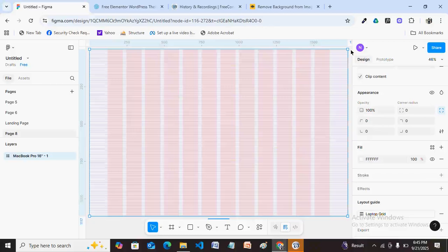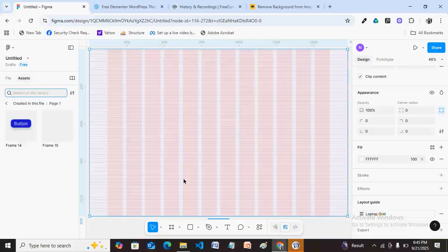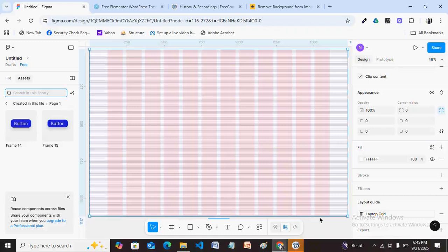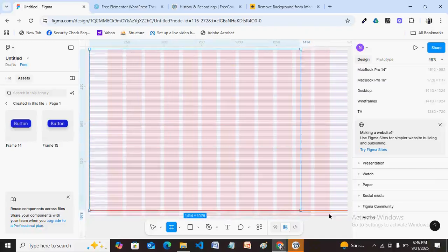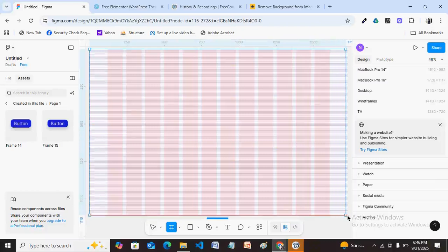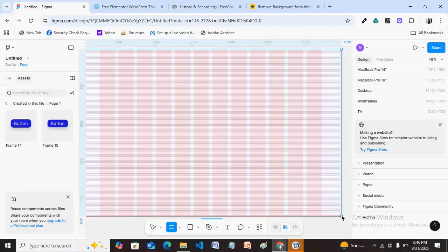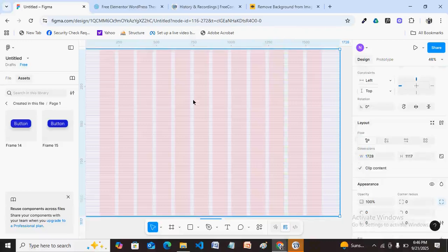So what I'm going to do is go to my assets. Before that, you notice that we have a kind of blue background and image on this particular section of the design we have followed. So I will come over here now, create another frame and give it the same size of what I have here. Figma can help us to do that. So on this now I can select my image to be on it.